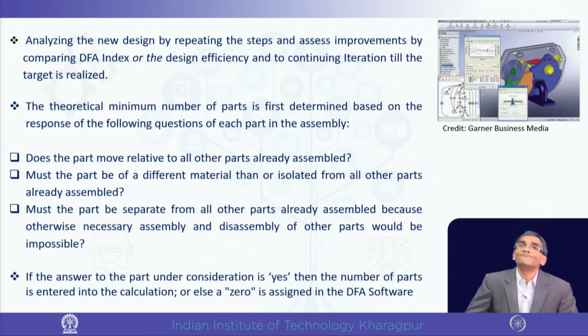What is this? Now, a part, if it can be combined into one instead of being separate, that is the advantage, so that we can bring the number to a minimum. So, if there are 2-3 parts being machined, fabricated and added, instead we can mold it through a casting process, and in one part multiple configurations can be brought in. So, it will become one part.